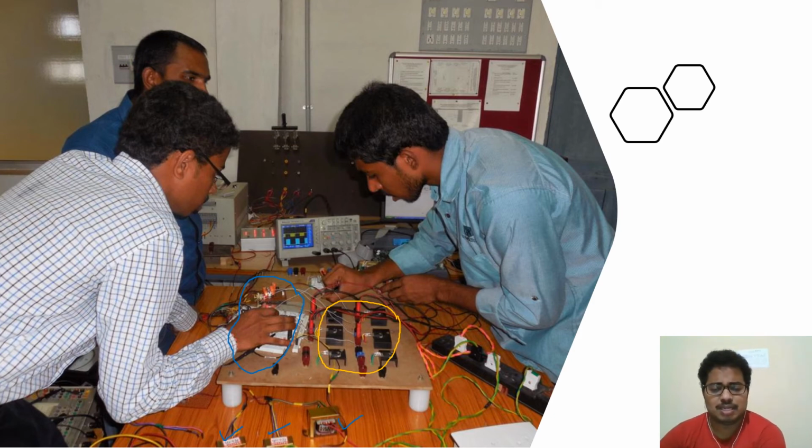Yes, these details I will post in my upcoming videos, like part 1, part 2, like that. For time being, this is the supply, how we are generating the three-phase supply from DC. Whatever three-phase supply we got, we are going to give to an induction motor, and we are going to demonstrate how the speed of the induction motor is going to vary based on firing angle or pulse width modulation. So we can see it in the next video.